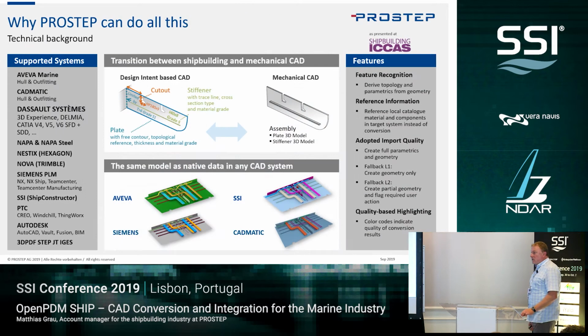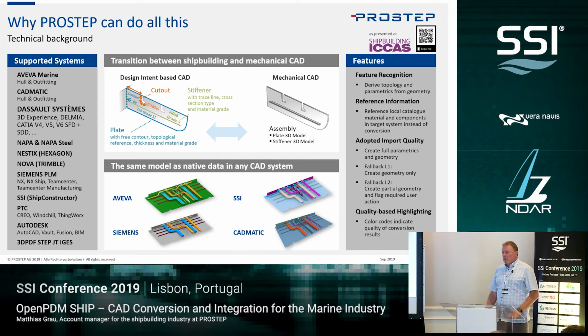CAD conversion as such, if it's about mechanical CAD systems, is something that has been resolved quite a long time ago. Especially this was the matter that was addressed by the STEP standard, and STEP basically nowadays is supported by most, if not all, of the mechanical CAD systems, and those systems can import-export STEP 3D models, with a few attributes attached to them, and that works more or less out of the box, no problem with that.